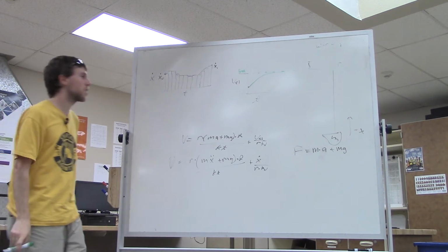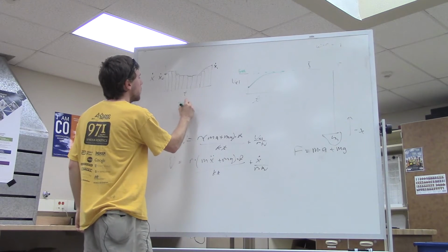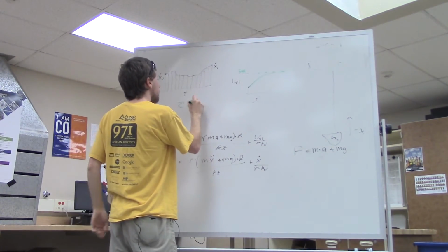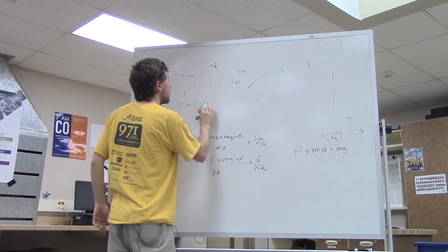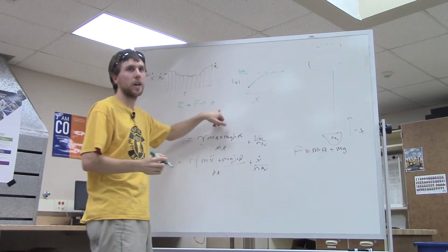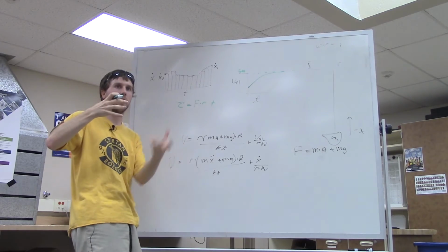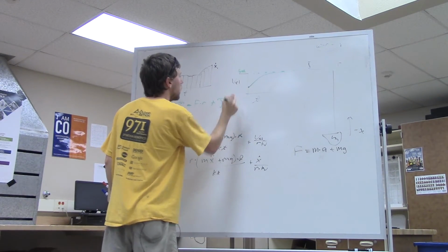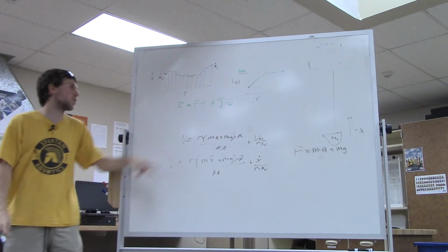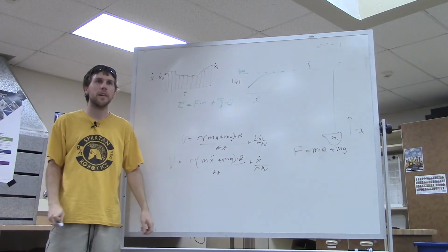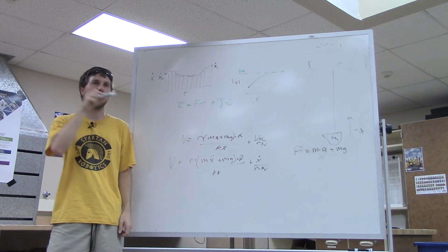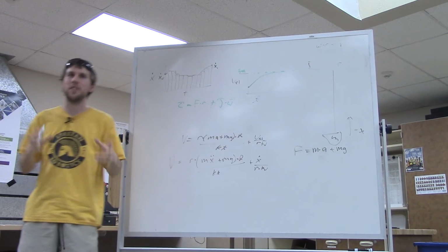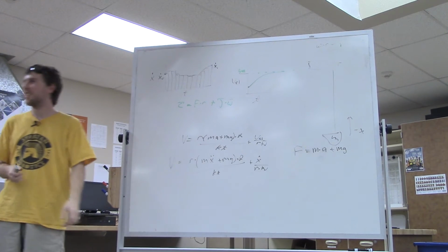Okay, so we can go over your... So we have the torque on the motor equals F, the force, times the radius. But then it'll be plus another torque on the motor, and that's the torque to accelerate up the winding, so that'll be J times omega double dot. This is the angular version of F equals ma. It's tau equals J omega double dot, where J is the moment of inertia of the windings, which is effectively the angular mass.